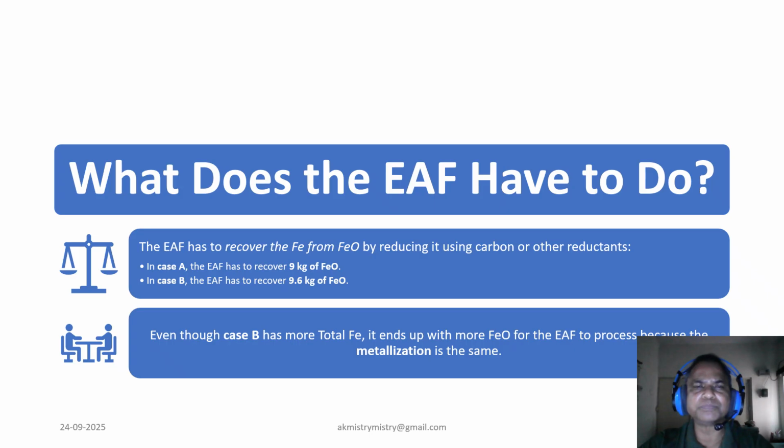So now coming to another consequence of the higher energy consumption. The reason is this FeO reduction, which is basically an endothermic reaction, and it means that we need a lot of heat. So the EAF must supply the additional energy to complete the reaction. The consequences are twofold. First, increased power consumption drives up production cost, and second, it leads to a longer tap-to-tap time, which reduces the overall productivity of the furnace.